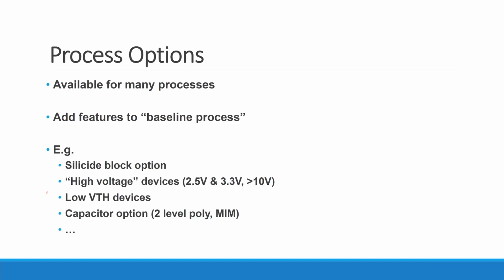Another one that would be really nice if it was trustworthy, and I'll explain what I mean by that in a second, is this: a lot of times in analog mixed signal, the biggest complaint people have about these modern technologies is that the supply voltage is just too low. Okay? And oftentimes you just run out of headroom to fit things inside of that supply voltage. So in some circuits, just the threshold voltage that you use on the device is kind of totally wasted, right? Because in analog, I'm trying to burn current through that thing the entire time, so I'm always trying to put some static bias on there.